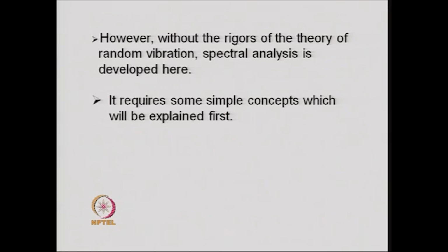So, let us look at these concepts again, starting with the definition of the power spectral density function and some other concepts that will be required somewhat in regard to random vibration analysis. However, we will not go through all the rigors of the random vibration analysis over here. We will simplify our spectral analysis technique by assuming the earthquake process not only to be stationary, but also ergodic.